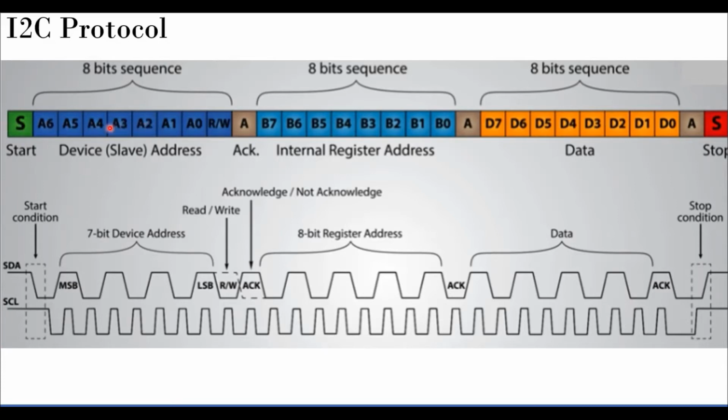Remember here it's a 7-bit address in this case. So if it is a 10-bit address, we'll have A0 to A9 here. So here it's a 7-bit address. I will put the 7-bit address plus I specify I want to read or write. Okay, so that's an important aspect. So once I do that, I wait for the acknowledgement. Okay, so this is something like how the SDA line will switch. For each clock line, I'll have the MSB, and so on. Then I will have read/write, and then the acknowledgement.